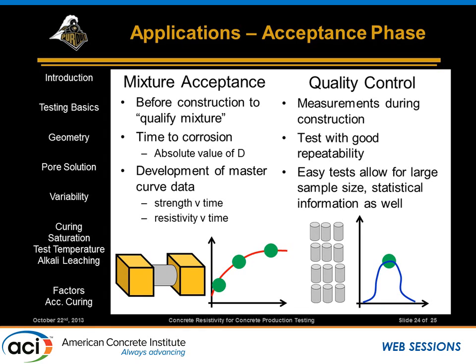What we have is really significant changes in the layers, and that surface layer leaches much faster than the core does. So what you can actually see is the ratio between surface and bulk changes dramatically, and it gives you some results that really look funny. If you start plotting them over time, you actually get a huge change. So the surface resistivity is much more affected at very early ages, and I think it's much more sensitive to the overall system that you're looking at. But it happens in both. It's just a bigger portion of both. And you can easily model it, and it's been done.